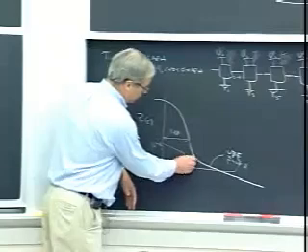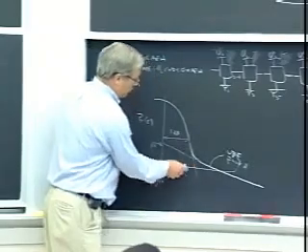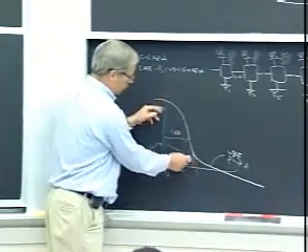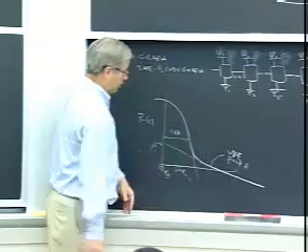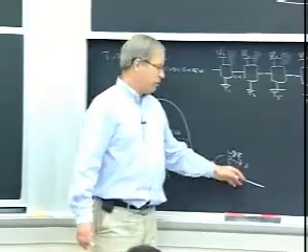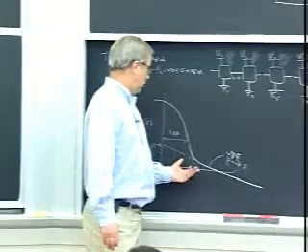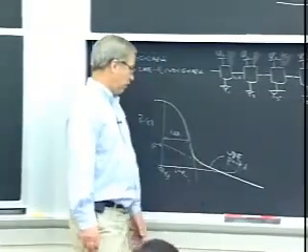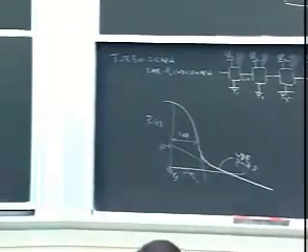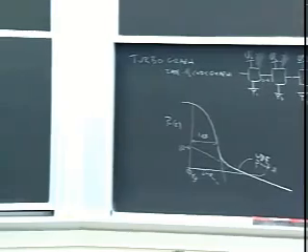You can think of these as being 2 types of curve. This is the iterative decoding curve. This is simple maximum likelihood decoding when you have minimum distance of d with a small error coefficient. And so this error floor is an important issue for turbo codes.